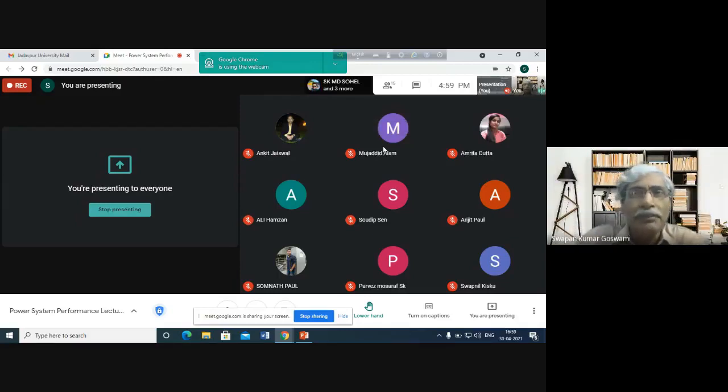So the main purpose of using bundle conductor is not stability, not the improvement of stability. It is rather the improvement of the performance of the conductor in connection with the occurrence of corona. So to avoid corona, we shall be using bundle conductors in high voltage systems. Okay. Always, the higher the system voltage, the more conductors will be used in the bundle.